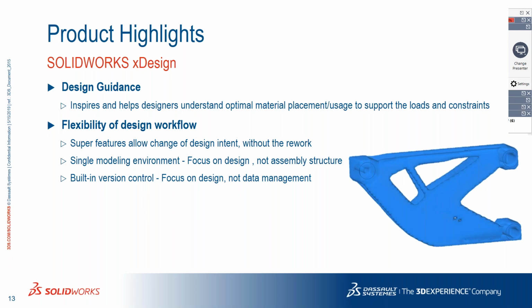I just need to edit the extrude feature and switch it to sweep. It is as easy as this. And something like a fillet one wants to convert to chamfer, or chamfer to fillet, everything is interchangeable. So the super feature is something that people really appreciate, especially at the ideation stage.